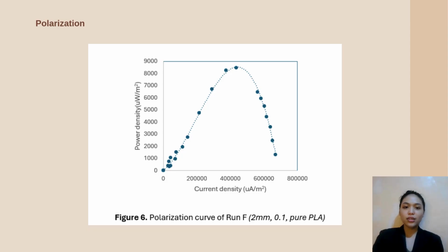Additionally, the results highlight a relationship between resolution and separator thickness, where at 0.1 resolution, a thicker separator enhances stability and performance, while at 0.2 resolution, a thinner separator maximizes material efficiency and minimizes resistance, showcasing how variations in these parameters influence power output.